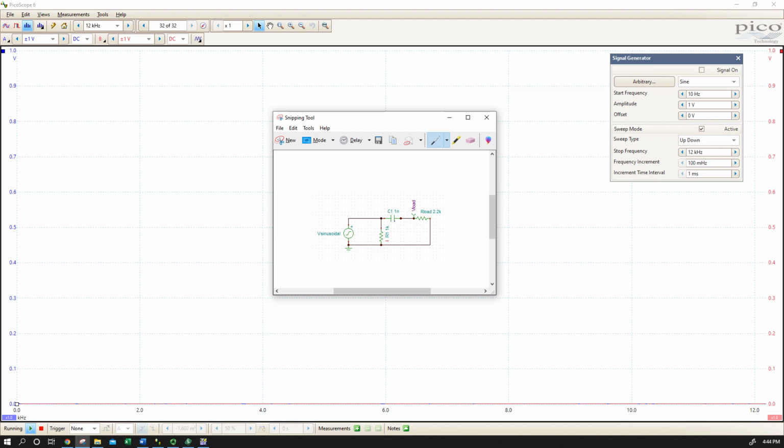capacitive reactance as I go from a high frequency to a low. Of course, I'm going to sweep the other way. So I'm going to start with a really low frequency, and as I am near DC, of course, this capacitor is going to act like an open, so the load resistor is not going to really see any of the total circuit voltage.